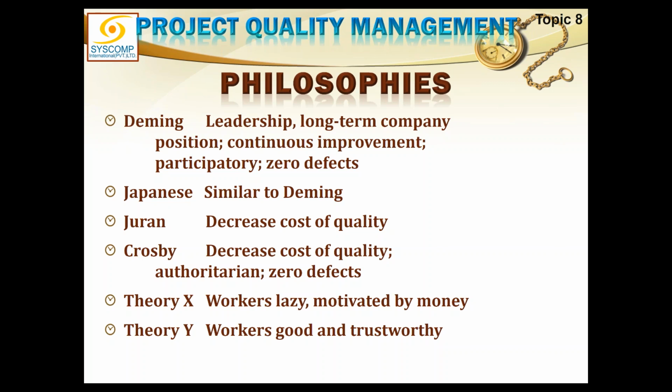They were accepting 99.74% as good, but 0.26% means in a million they are ready to accept about 65,000 defects. So they said this is too big. The Japanese are talking about zero defect. We are having 65,000 defects. So where do we stand? We are no good. That is why Japanese products are better than us. So they started working on the theory of how to improve it, and they found that three deviations of standard deviation, 3 plus and 3 minus, are not enough. They are just giving us an accuracy of 65,000 defects.